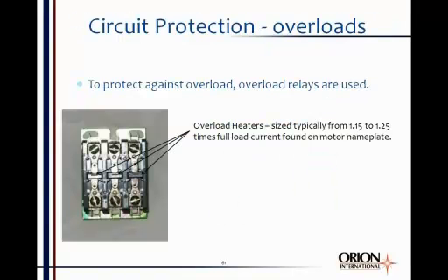Now, those are overcurrent protection. What about overload protection? Overloads are generally a result of trying to use a motor inappropriately. You know, if you try to use a 5-horsepower motor to do a 10-horsepower motor's job, then the motor will be in an overloaded situation.